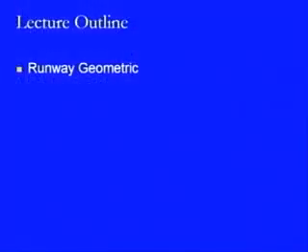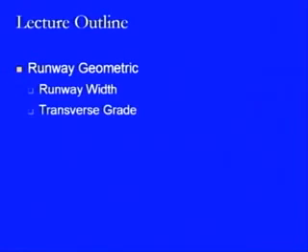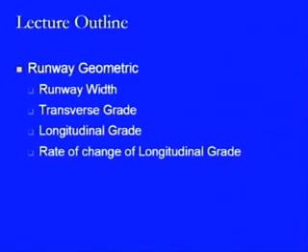In continuation of the same, in today's lecture we will be concentrating on the various geometric features of the runway strip. Therefore, this lecture has been outlined in the form of runway geometrics, wherein we will be discussing the runway width, the transverse grade, the longitudinal grade, the rate of change of longitudinal grade, and side distance requirements. So, we start with the initial geometric condition, that is the length of the runway strip.